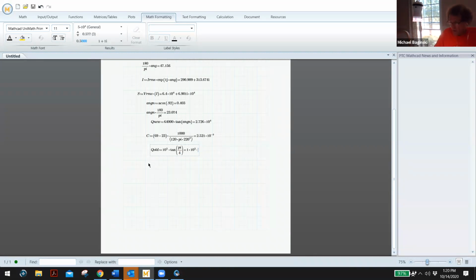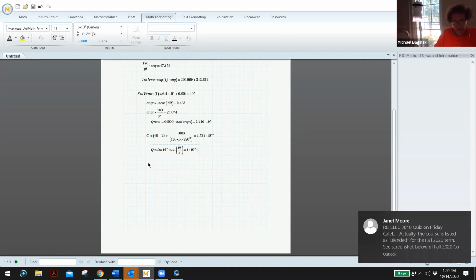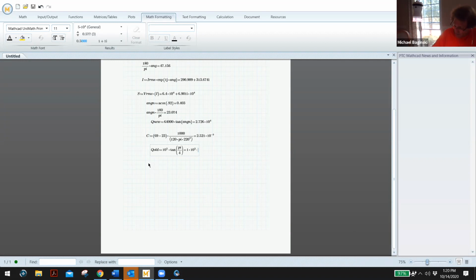Now, what we want to do is reduce this. We want to reduce this. So the next thing we do, to get the new one, we have to take a look at what they actually want. Now, when we draw this, we're going to redraw the power triangle, but according to the new formula. So what he wants is, by the addition of a capacitor, he wants this. You'll always have the same amount of real power. So the real power here is still 100 kW.